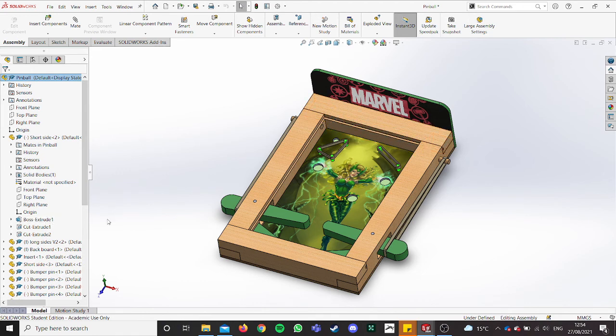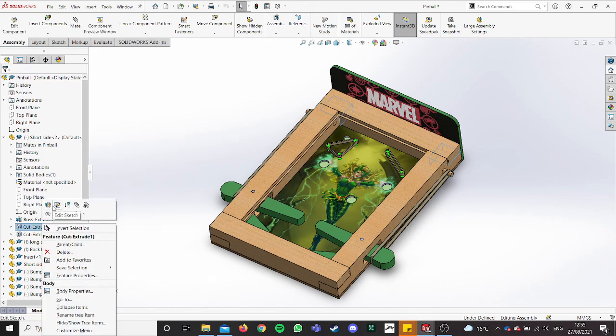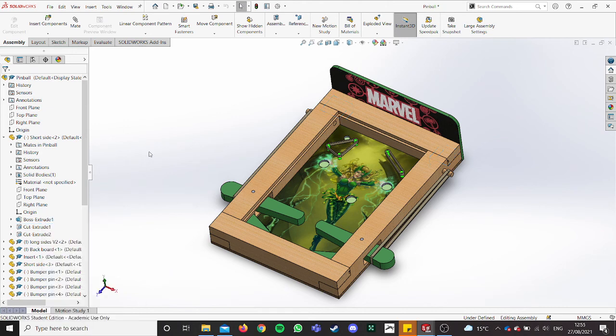While I'm here, the important thing with SolidWorks is that you're able to undo actions and change actions, and you can change dimensions and various other aspects. So what I can do is right click on this particular extruded cut. You'll notice that if you look here on the screen where the cursor is now, it's highlighted in orange because it shows you what I did at the time. If I right click it, I then have options that pop up, and you'll use the edit feature and the edit sketch tools routinely. So that's a right click on the button, and then you can get access there.